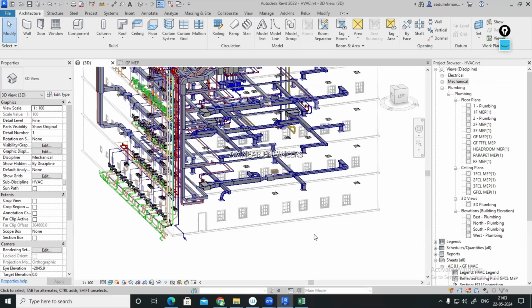Okay. And as you know, the minimum pipe diameter as per the pipe schedule method, or even if hydraulic calculation, minimum pipe size we will be using 25 mm only. The pipe material for firefighting we will be using schedule 40 carbon steel pipe. And the joints should be welded.